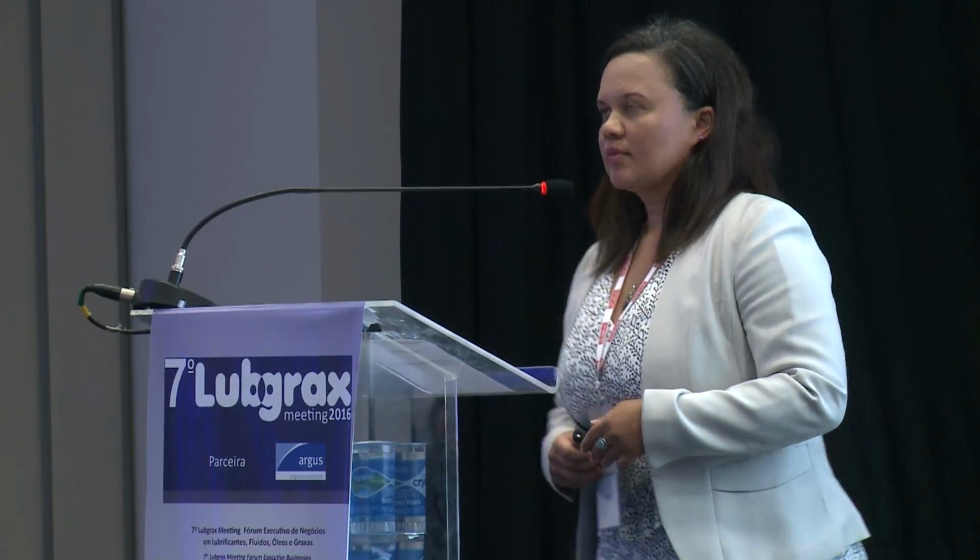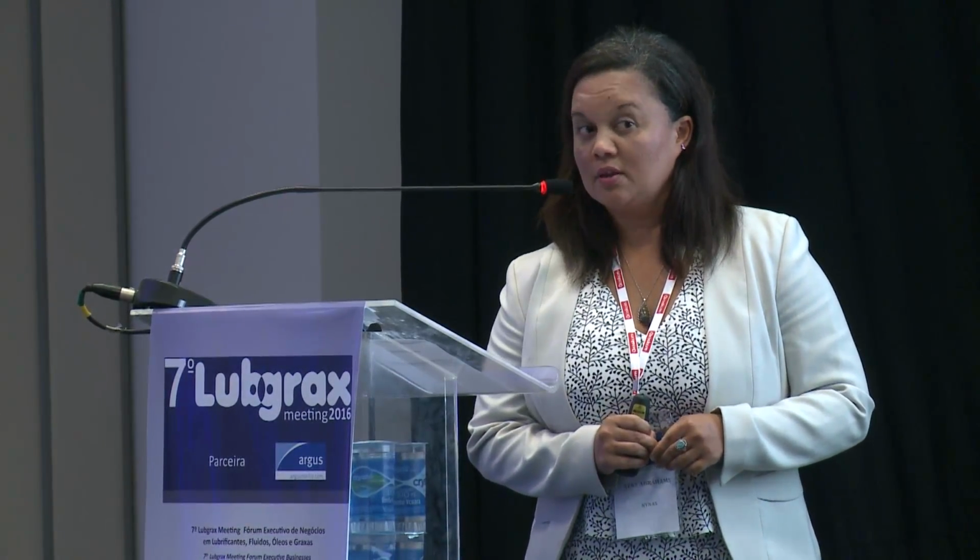Right, so because we saw this interesting thing with the pour point behavior, we were curious to see how the low temperature behavior of the grease was going to be impacted by this. So there's a test called the flow pressure. Maybe most of you are familiar with it. You just take a small bit of grease in a conical nozzle and you apply a pressure as the temperature is dropped significantly to very low ranges, and you note the pressure at which the grease begins to move. So this is a reflection of the pumpability or the flowability of a grease at a very low temperature. So we've plotted it over a temperature scale.